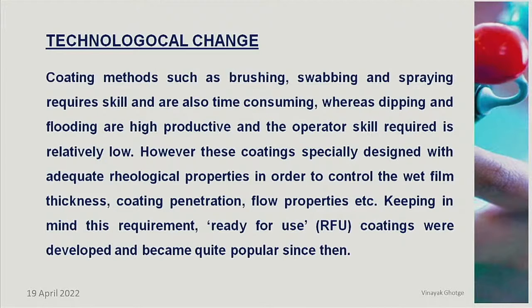However, such coatings are specially designed with adequate rheological properties in order to control the wet film thickness, coating penetration, flow properties, etc. And keeping in mind these requirements, ready for use coatings were developed. That means coatings in ready for use or paste form. And then these coatings become very popular.